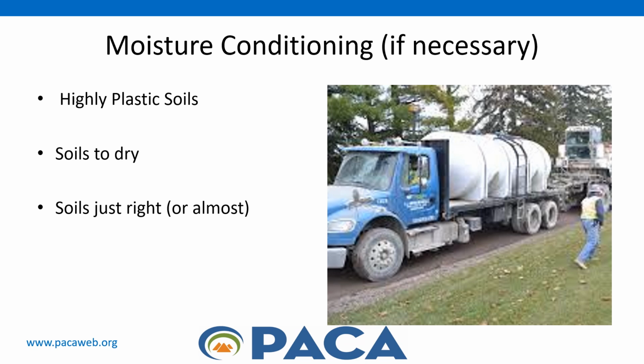For overly wet soils, aeration of the soil may be necessary prior to the stabilization process. That way, the soil can be pre-treated with a moisture absorbent additive. For soils that are too dry, water can be added immediately before or during the initial pulverization process. A moisture content near the optimum moisture content can facilitate the pulverization process, especially for highly plastic soils or expansive clays.